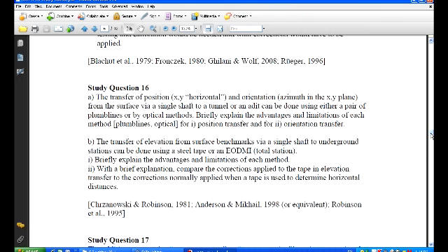The advantages then with the plumb line would be that there is almost no limit to how deep you can go. The deeper you go, the heavier the wire and the greater the weight that's put onto the end of it. And we have ways of calculating what sort of variation there would be. And as you notice from those formulas, the deeper you go with the plumb line, the more uncertainty would be associated with the transfer of the horizontal position.